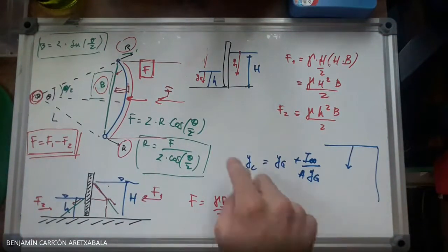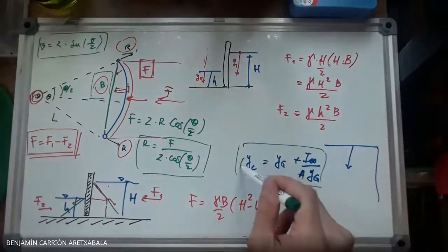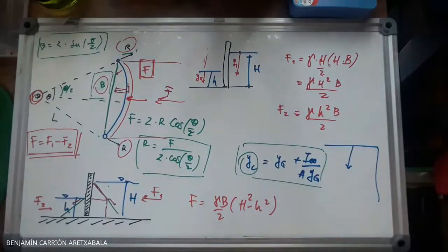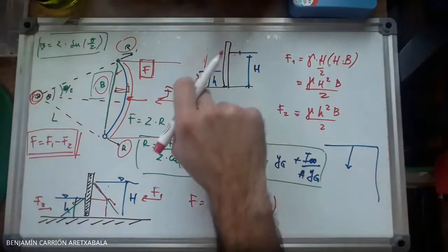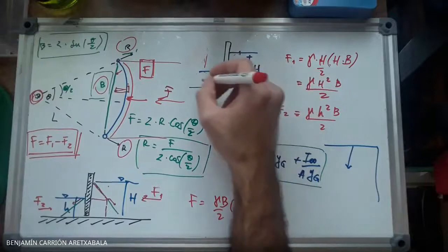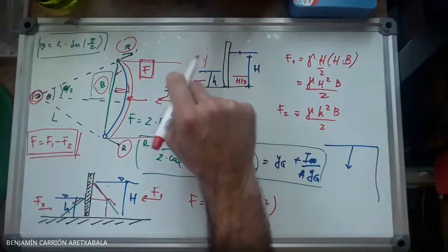Okay, so you could have used this equation, but you had to keep in mind that both yc1 and yc2 were referring to different vertical datums or vertical reference. So you needed to keep that in mind. Many of you, though, realized that the point of application is just h third at each side, which I also told you during class, right?